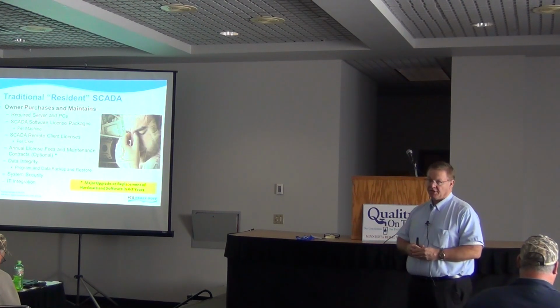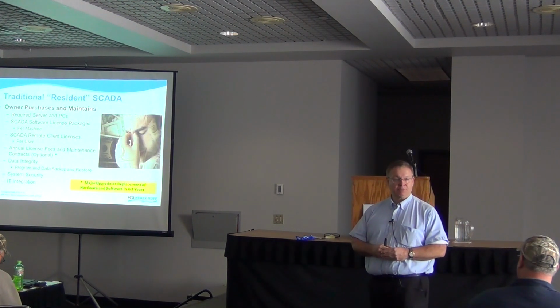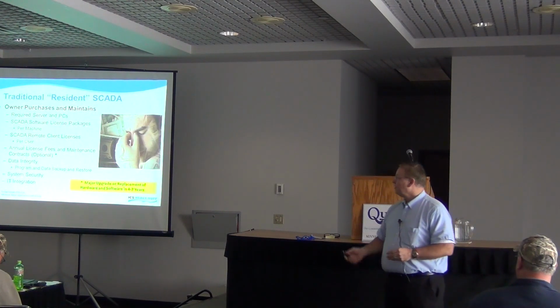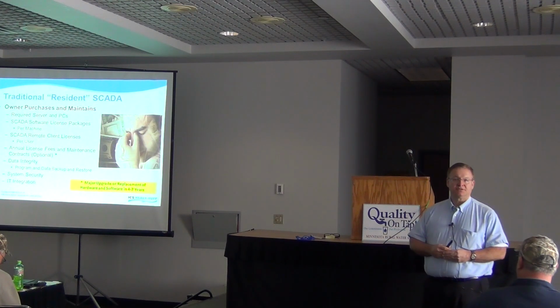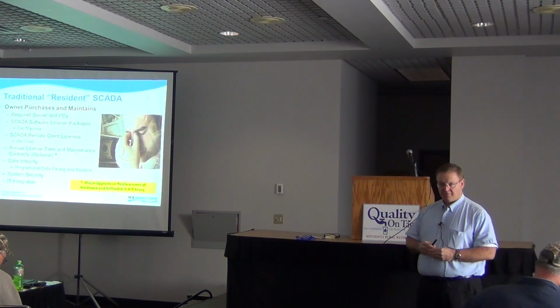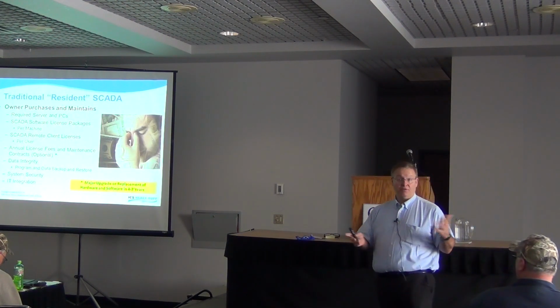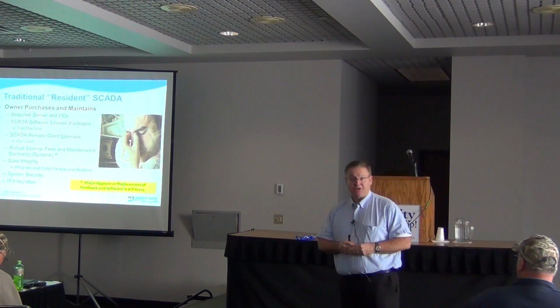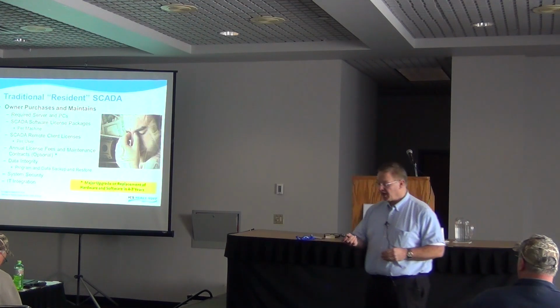You may need some IT integration in there too, so for a complicated SCADA system, you've got a lot of networking going on, you may actually have to employ the services of an IT person to help that out. Then, that equipment is probably going to need to be upgraded every 4 to 7 years or so. Sometimes you can go longer, and some groups actually end up going shorter. But you're going to be probably looking at some kind of an upgrade, and that upgrade is going to consist of hardware and upgrades in your software. Many of you probably have already gone through upgrades, and you're almost paying as much for that upgrade as you did for the original system. So there's quite a bit of cost that can go along with it.